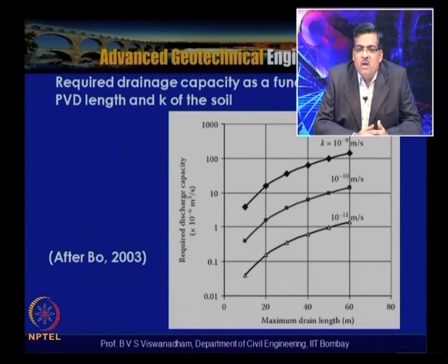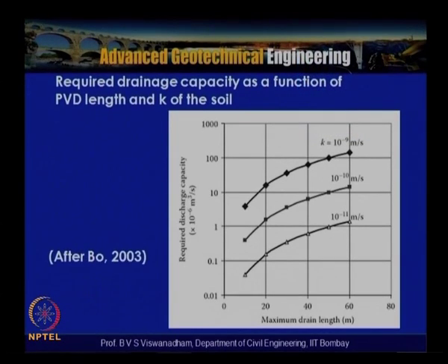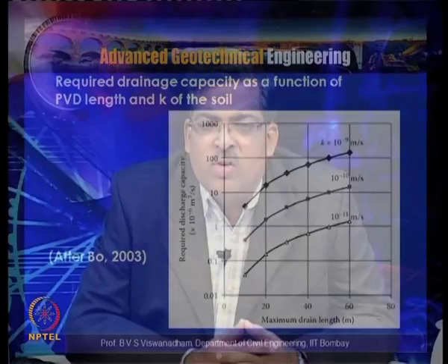If you look into the liquefaction mitigation issues with sand or silty sand, first of all the installation in these sandy soil conditions can cause a worry, because of the frictional resistance offered to the mandrel, the tool which is used for installing these PVDs. And with the decrease in permeability, there is an increase in the required target discharge capacity for a given length.